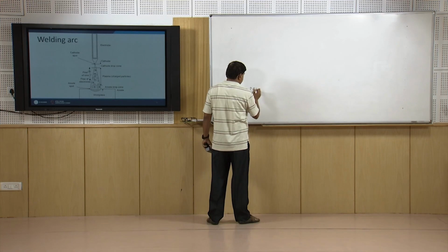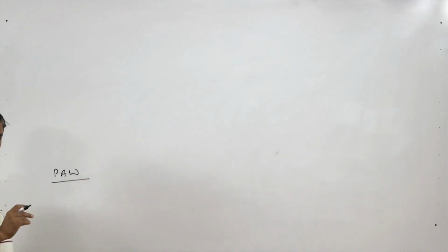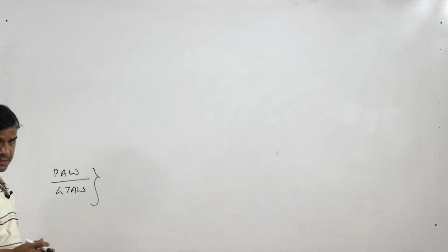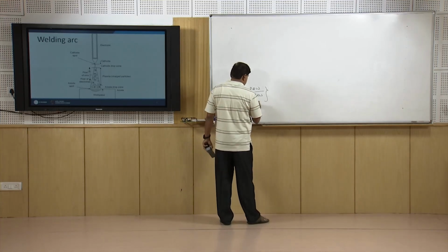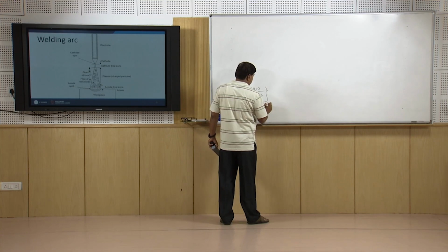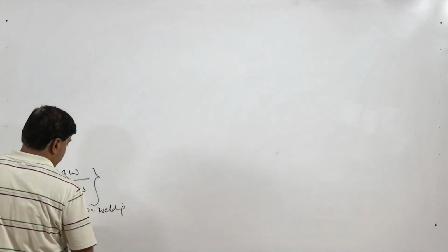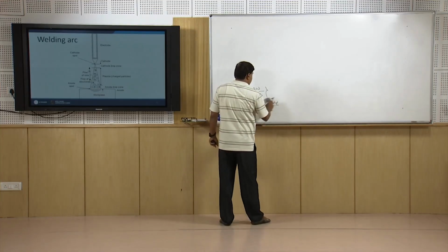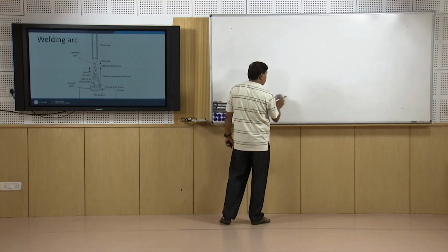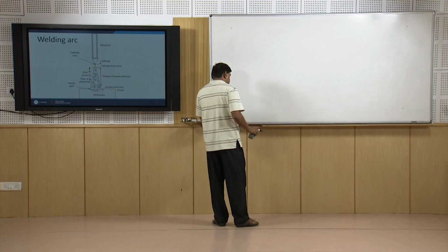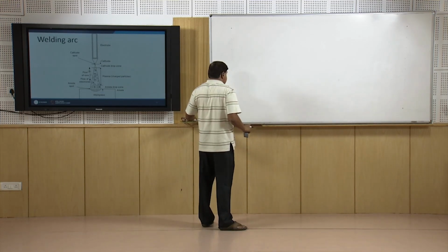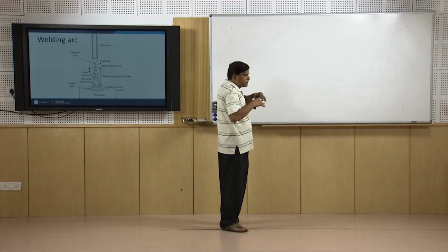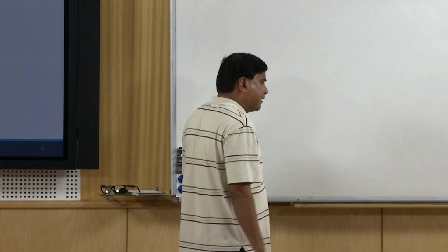So, plasma welding and all other automatic gas tungsten arc welding, wherever we find that the contact is not suitable, or in automatic welding processes where it is not feasible, wherever automation has been implemented, we want that the arc is initiated without direct contact, rather than feeding the electrode to the workpiece for making contact and initiating the arc. So, these are the two ways by which the arc is initiated. These basics are applicable to the entire range of arc welding processes.